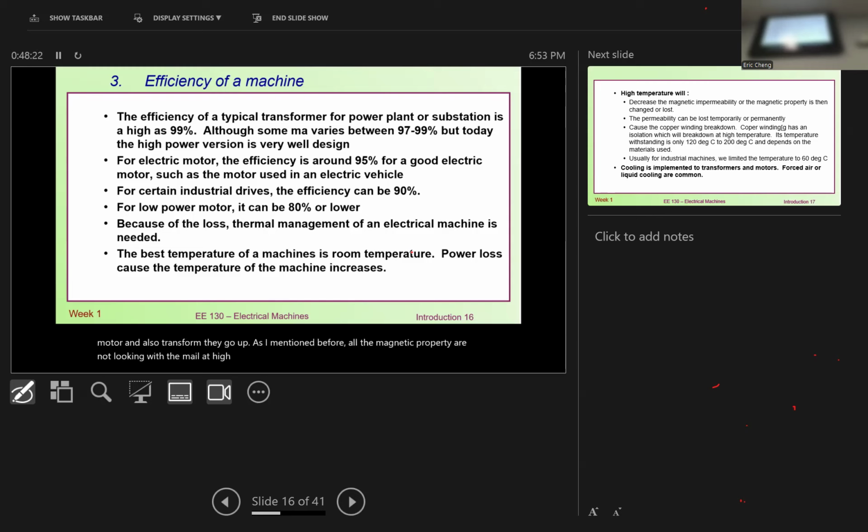The magnetization may be lost and the permeability will drop. If you increase the temperature, the magnetization will drop, and the inductance will drop, because higher magnetic flux will need more saturation. That's a kind of avalanche effect. So temperature is one of the issues.